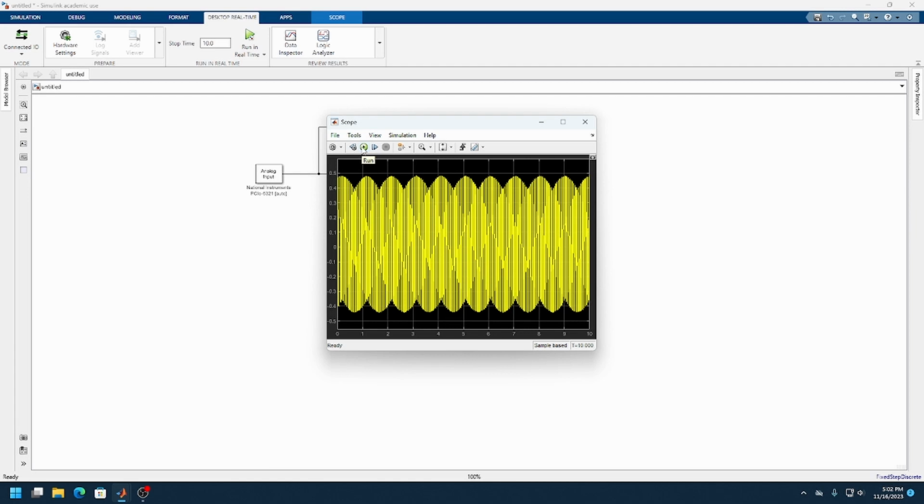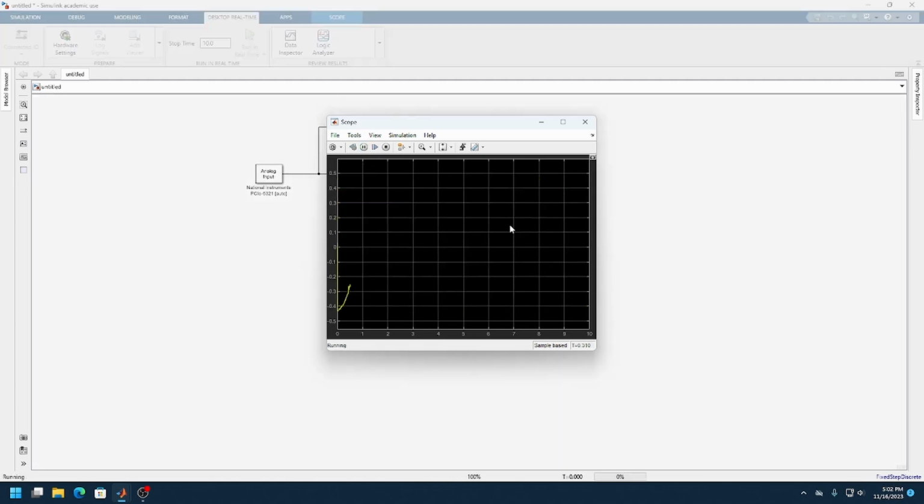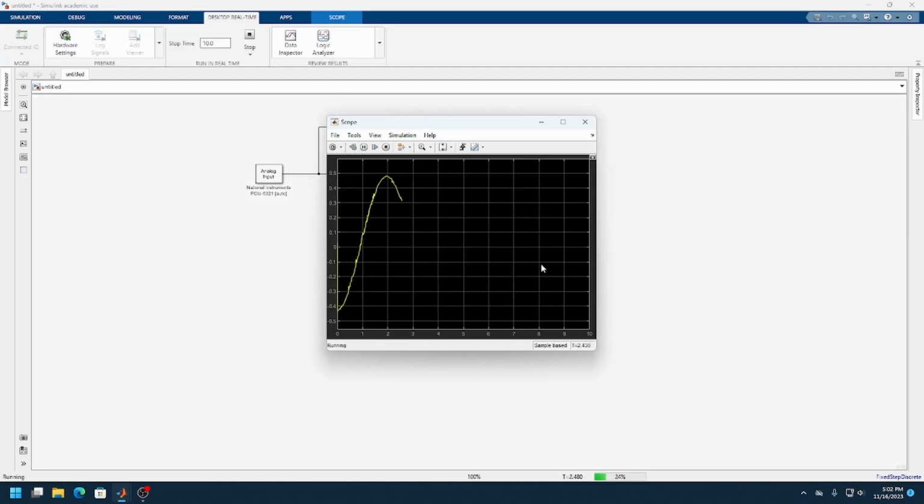Make sure you adjust it to be almost exactly what you need it to be. Otherwise, you'll get the same sample time issues we had at 20 Hertz. So you can see a little ticks here and there, but it's relatively a good sine wave. Whenever you're running these, make sure that you're taking pictures for your oscilloscope and pictures here on the scope. You'll continue to do this for your other frequencies.